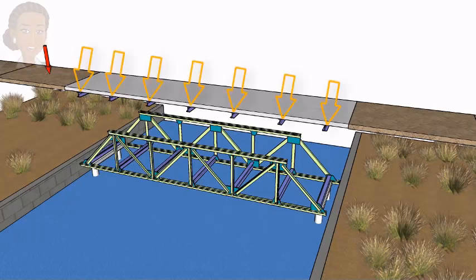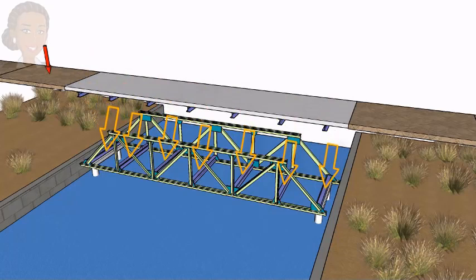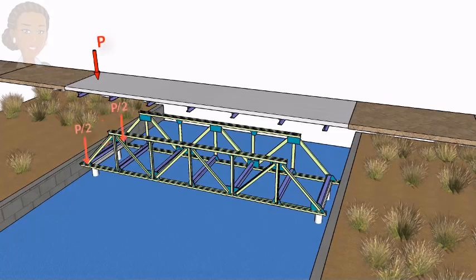Here are the beams supporting the deck, and here are the exact same beams shown attached to the truss joints. When the truck enters the bridge, when the load is directly above the outermost beam, the entire load transfers to that beam. The load is then distributed to the 2 truss joints supporting the beam. When the truck moves forward, when it is somewhere between the first beam and the second beam, the load is distributed between the 2 beams in proportion to its distance from them. In turn, the beam loads are transferred to their respective end truss joints, like this.